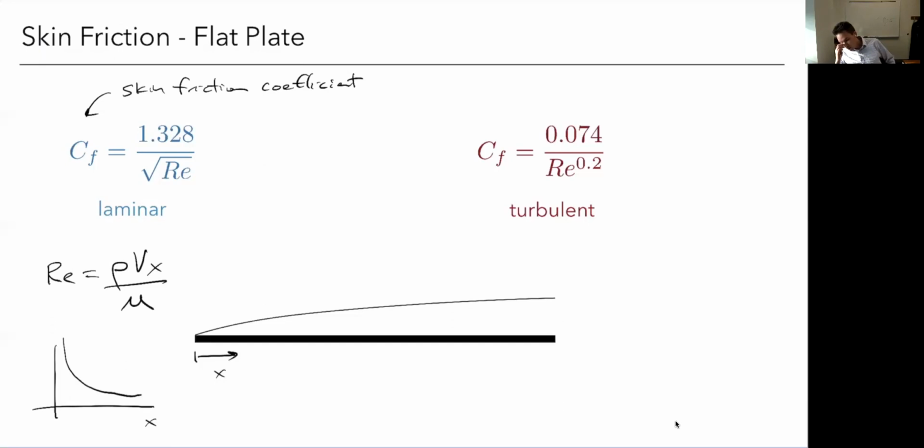So if you're designing your airplane, you'll see a lot of these model airplanes will have tape right towards the front, but not put tape towards the back of the wing. And the reason for it is that I get the best bang for my buck by putting it towards the front. As I put it towards the back, it may help decrease drag a bit, but it adds weight and it may not be as useful a trade-off. Whereas towards the front, that weight penalty is worth decreasing some of that drag.